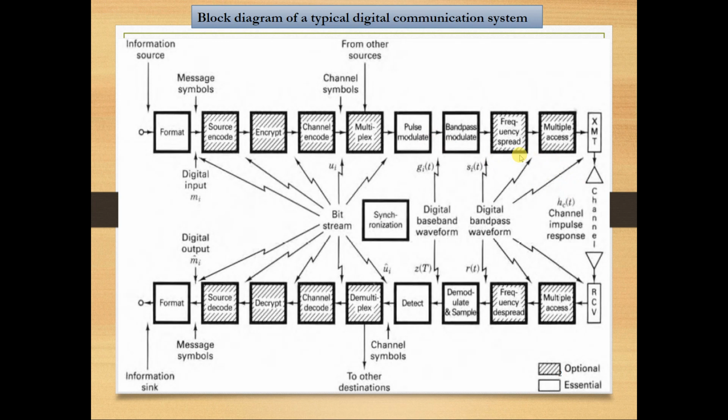So this is why we need modulation. Why did I need this step? Because I will not be able to transmit my data and make it go through the channel if I just send it as is. But when I put it in a carrier frequency and this frequency is within the range of the channel filter, then I make sure that my signal will pass through.